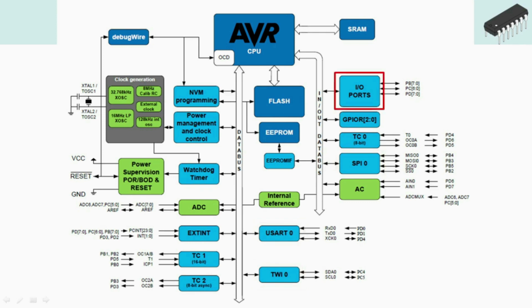The microcontroller has 3 GPIO input-output ports, which include 23 input-output lines. Ports B and D are 8-bit, and the general-purpose input-output is used to communicate with peripherals. The individual GPIO pins can be configured independently and have symmetric drive capabilities. That means the pin can source and sink the same amount of current. When configured as input-output, the microcontroller supports two external interrupts and 23 pin change interrupts. It also supports interrupts from the watchdog timer and other timers, USART, EEPROM, the A-to-D converter and the analog comparator.